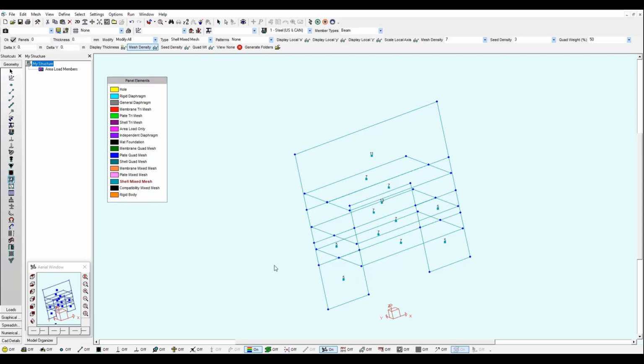Please note the meshing algorithm automatically finds the intersection of all these panels and splits them in different panels to ensure meshing consistency at the intersections. Also, the mesh density changes because the size of the panels change after the splitting operation. However, the algorithm tries to keep the mesh density the same as the original, unsplit version of these panels.